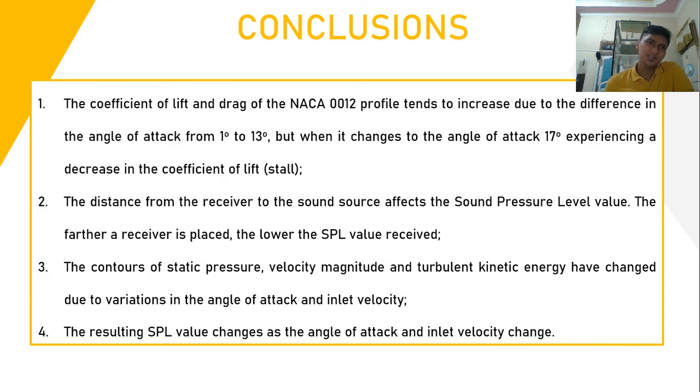The conclusions. First, the coefficients of lift and drag of the NACA 0012 profile tend to increase with the angle of attack from 1 degree to 30 degrees, but when it changes to an angle of attack of 70 degrees there is a decrease in the coefficient of lift, which we call stall. Second, the distance from the receiver to the sound source affects the sound pressure level value. The farther a receiver is placed, the lower the SPL value.